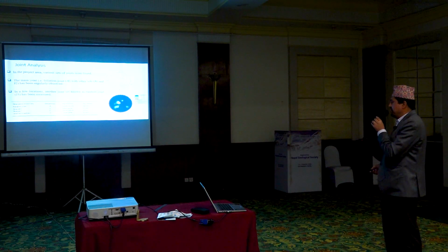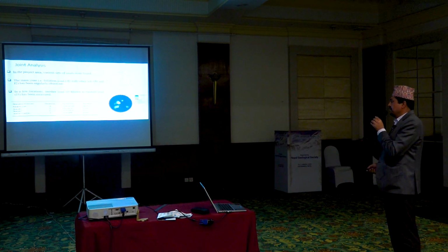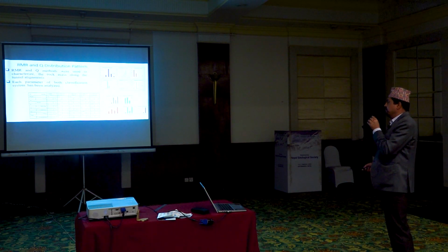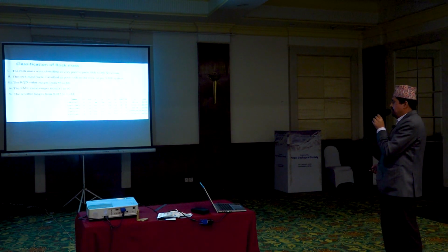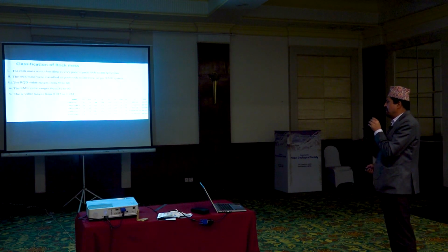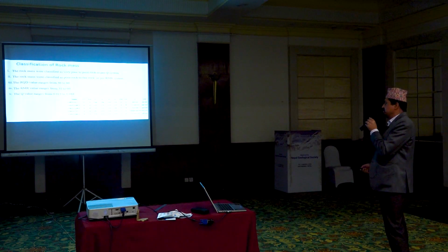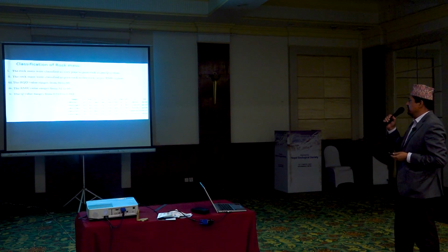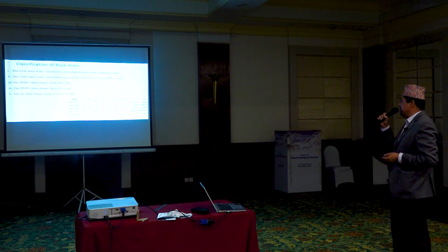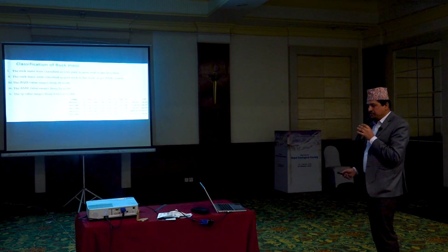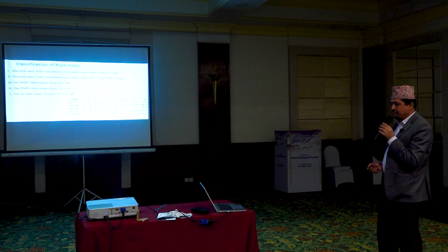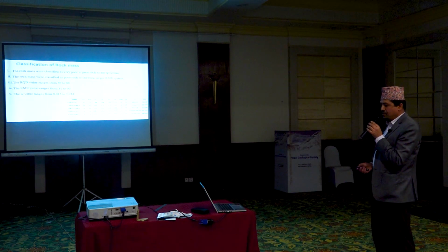For the analysis, we have done joint analysis, and we have encountered joint sets plus random joints. Similarly, to characterize the rock mass, detailed parameters of Q and RMR have been analyzed. For the classification of rock mass for Nearapala, as we look at the chart of the Q system, the rock mass lies from very poor to poor rock mass. Similarly, if we see the chart for RMR, it classifies poor rock to fair rock. The RQD value in the project area ranges from 30 to 80. Similarly, the RMR value is 31 to 60, and the Q value ranges from 0.013 to 1.